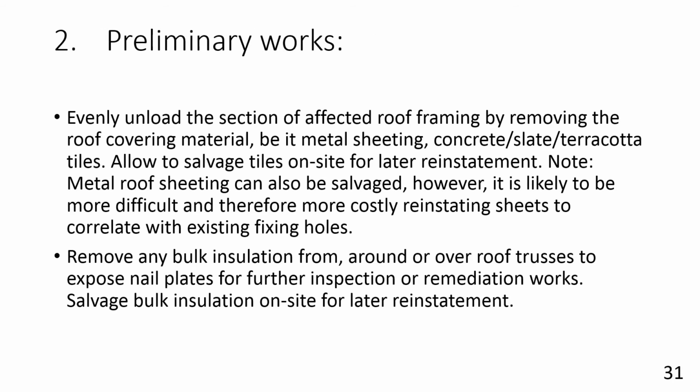The remediation scope of work is likely to entail preliminary works whereby roof coverings and other removable loaded items are evenly removed, unloading the subject defective trusses.